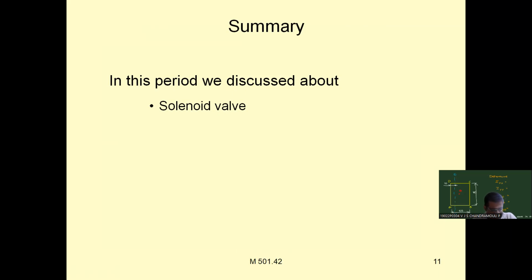And there are different types of dryers, like throwaway type dryers and refillable type dryers. Throwaway type dryers are used only once. Once the complete desiccant is used up, they can simply be thrown away and replaced with a new one. These throwaway type dryers are also called non-refillable or seal type dryers. The next one is refillable dryers. Once the desiccant material inside these refillable dryers is used up, it can be replaced. Only that desiccant material can be replaced, not the entire dryer.